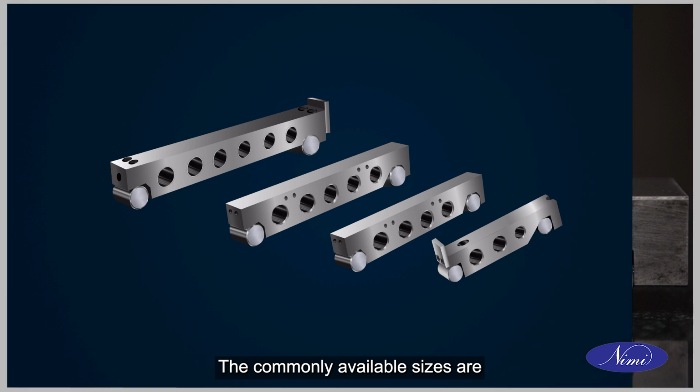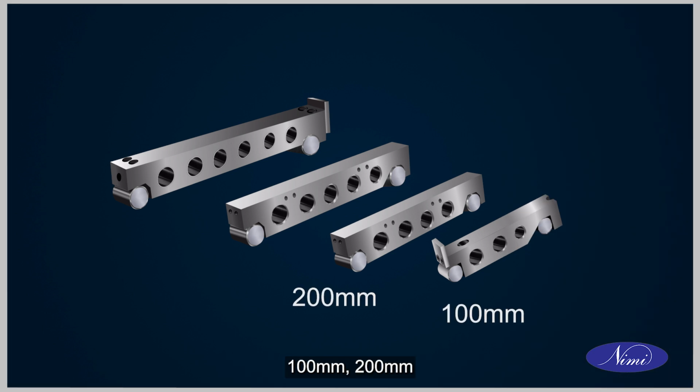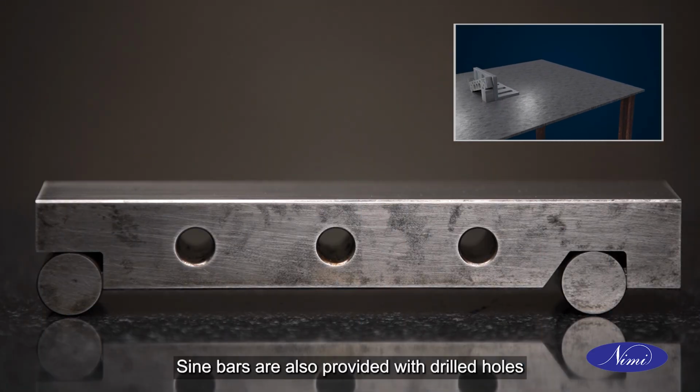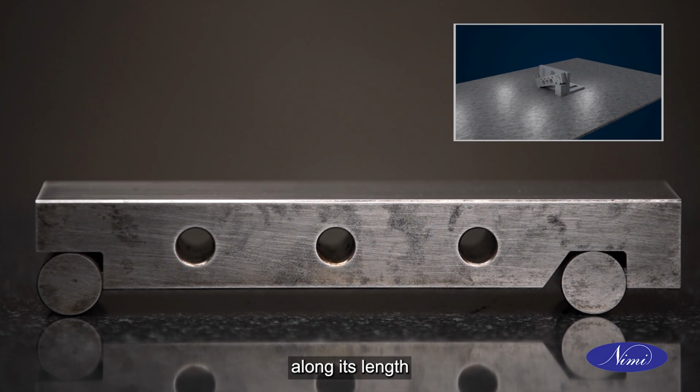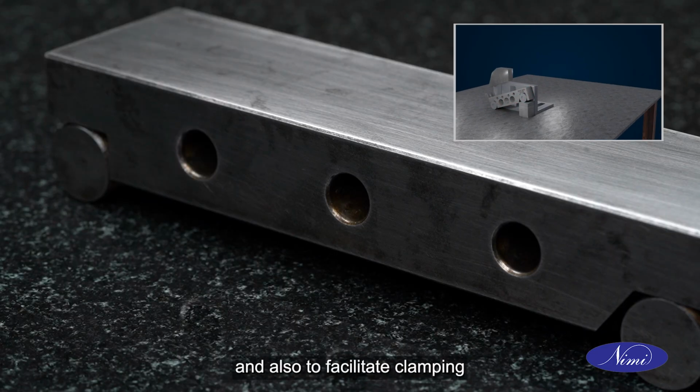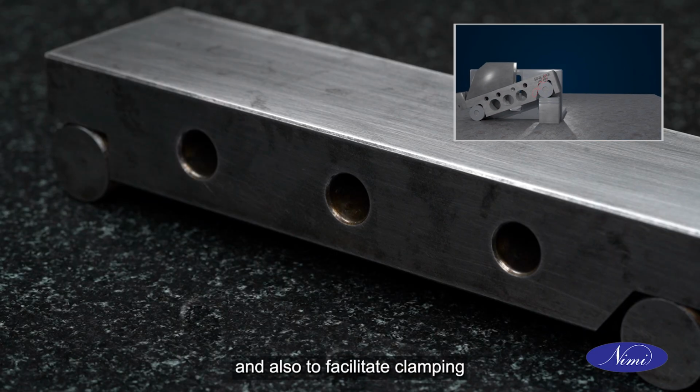The commonly available sizes are 100 mm, 200 mm, 250 mm, and 500 mm. Sine bars are also provided with drilled holes along its length to reduce the weight of the sine bar and also to facilitate clamping.